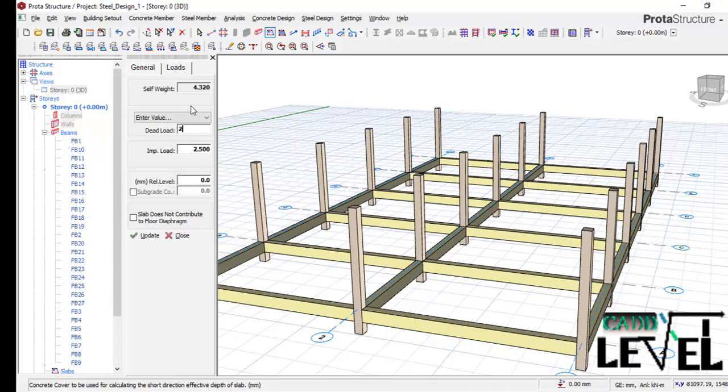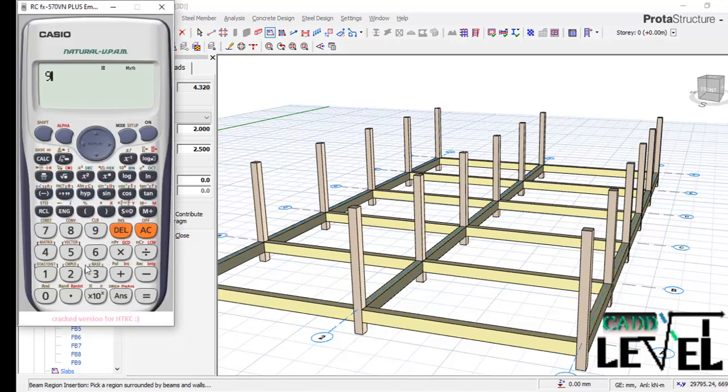Right? Then the reference level. We calculate the reference level. We have the thickness of the slab to be 180, so you have to do a simple calculation: the 900 millimeter DPC minus 180. If I activate the calculator to check that out, we have 900, which is the depth of the foundations, minus 180 equals 720.